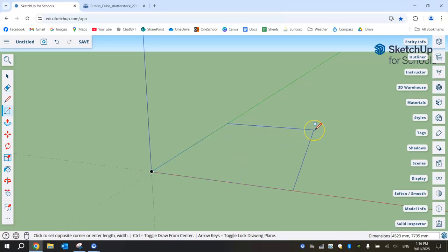So just be careful here. What I want you to do is click once to just draw a square, and without pressing anything else, I want you to type in 25,25 and press enter. That actually types into your dimensions box down the bottom here. So what we've done now is resize that square or rectangle you just drew to 25 by 25 millimeters. And that is very small.